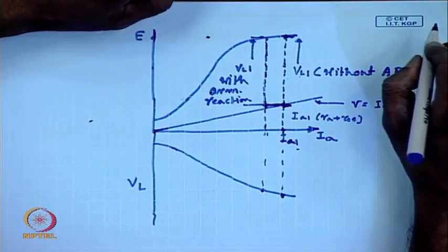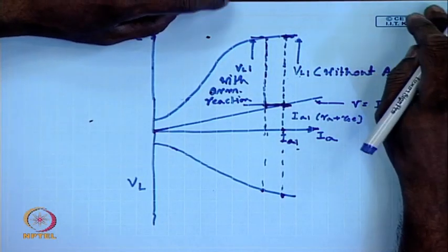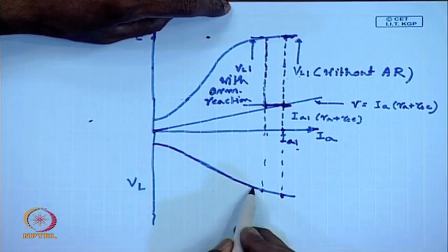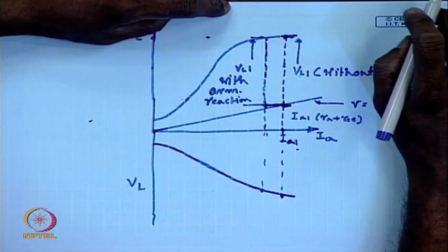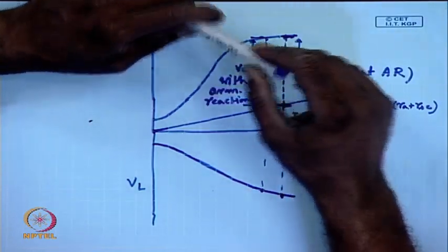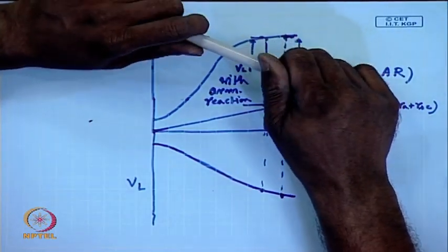One difference of these output characteristics with the shunt generator is that the output voltage varies over a wide range depending on the load current, which is expected, because the strength of the field flux is almost dictated by the load current. As the load current reduces, the field flux reduces, the generated voltage reduces, so the terminal voltage also reduces.